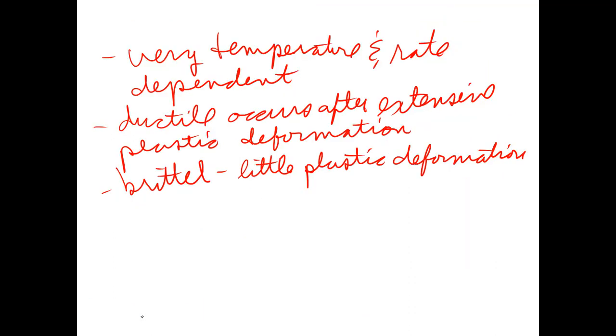Other characteristics of these surfaces are that the ductile type fracture is usually desirable from a use standpoint simply because the fracture might give an operator time to identify that the part is about to fail. But overall, we want to design to keep any plastic deformation from happening if at all possible.